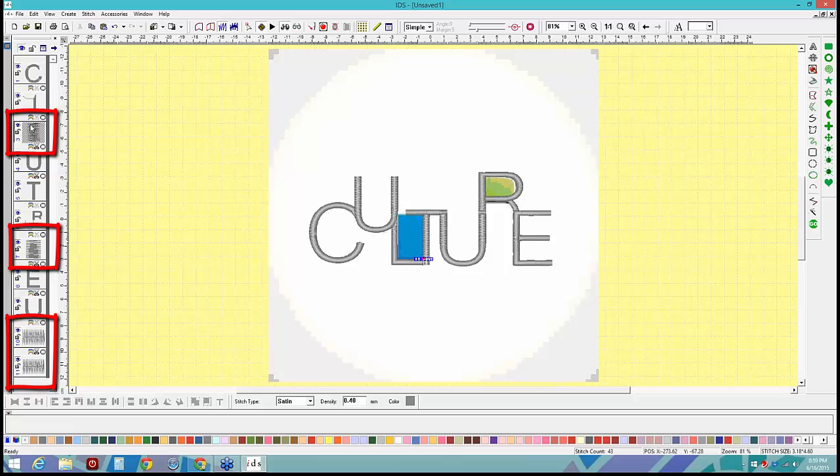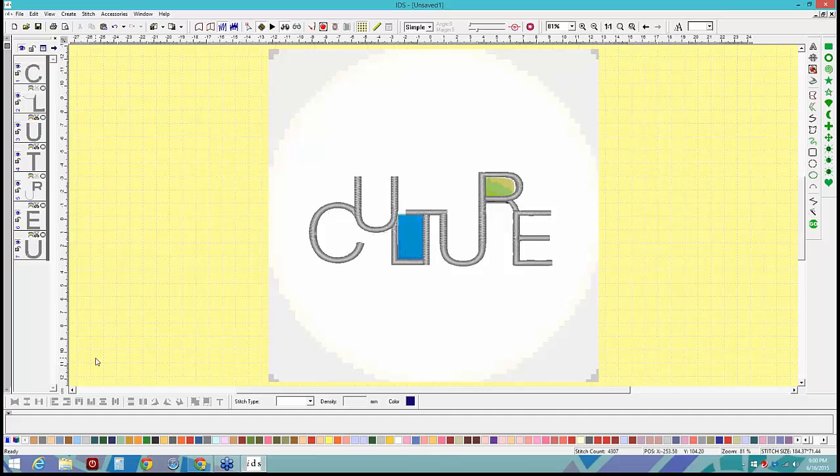See? Hold your control key and come down to the next little piece that needs to go. And you can see these little pieces all the way down here. You know that those are the pieces you sliced away. So just hold that control key and left click on them, and then continue to hold the control key and press delete. Now those are all gone, and what I have is maybe a little more editing here. I might adjust this width a little bit, but my design is running into itself pretty well.